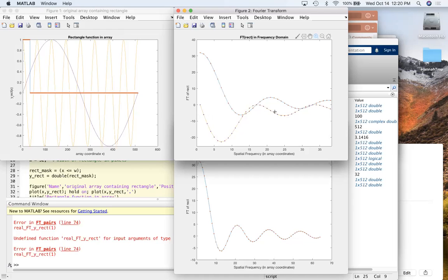These two should overlap at, so here at k equals 16, we will have a perfect cosine replicant inside here that integrates to 0, and that gives us 0 in the real part. And in a similar way, we get a perfect sine replicant of one full sine phase in there that integrates to 0.